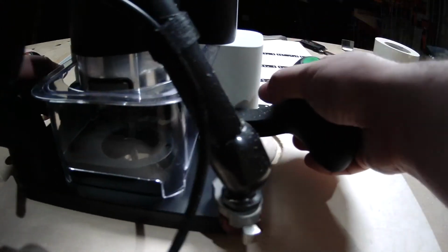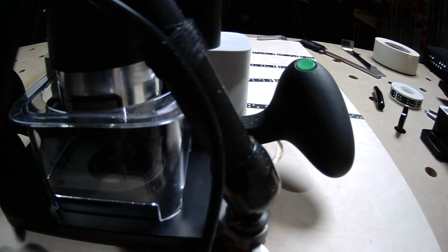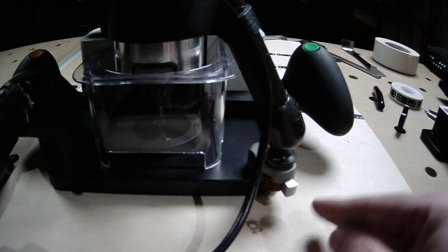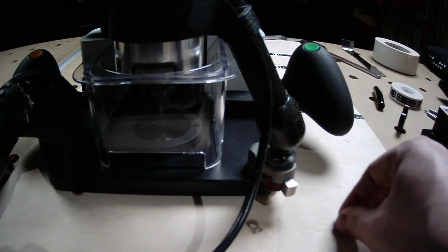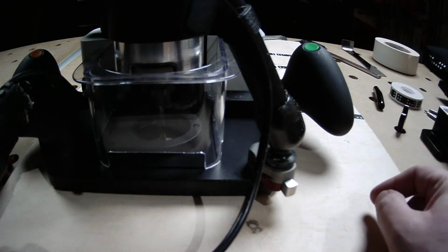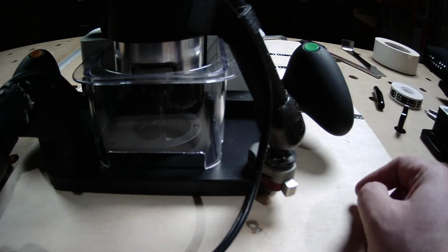If you're holding it loosely and letting it bounce around on the surface, you're going to see that in the bottom of the pocket, because it's really amazing how visible even a small change in height becomes. And you're never going to fully remove the witness marks at the bottom of a pocket, even on a regular CNC machine. Those are really hard to get rid of just with the machine. It's going to require some kind of finishing work after the fact, sanding with detail sanders.